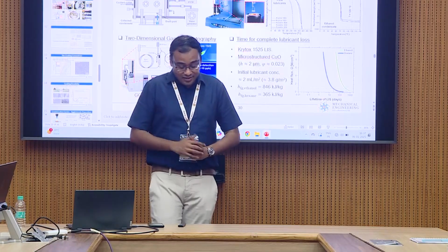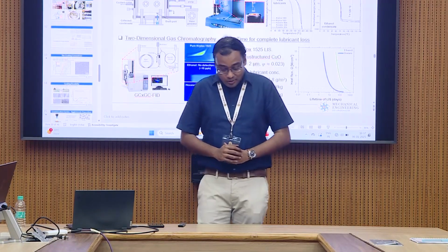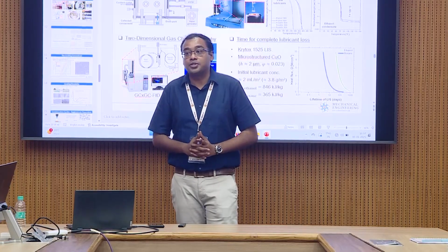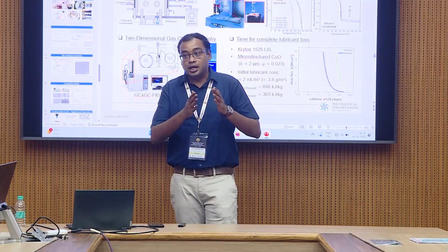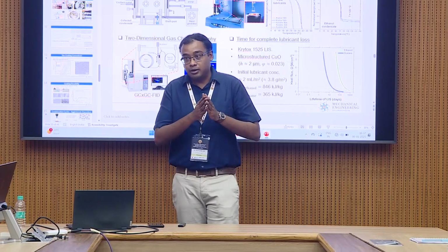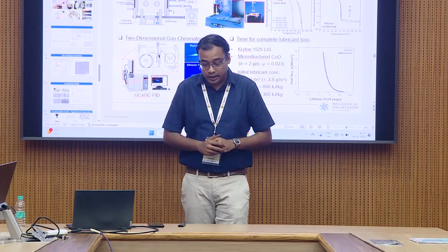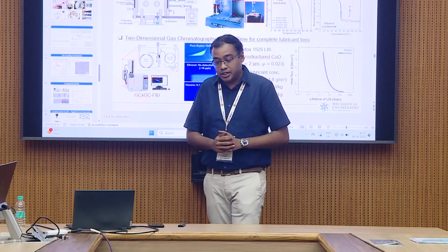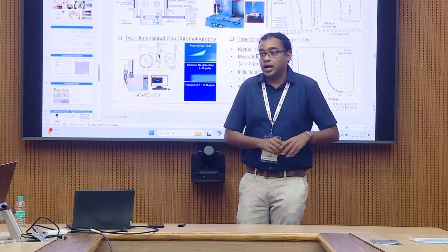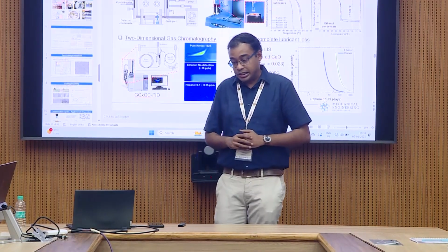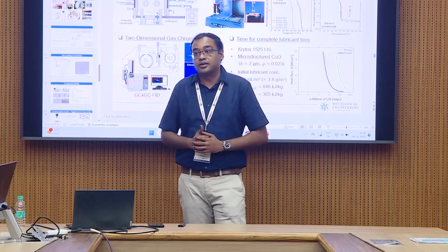Right. That's a great question, Professor. So, in terms of the conditions, there are regimes where, let's say, at a particular degree of subcooling, particular saturation pressure, we will get one form as opposed to the other. But in most applications, that is not in our control. As a thermal engineer, we don't get to control the vapor or the conditions, and therefore we have to rely on the surface.